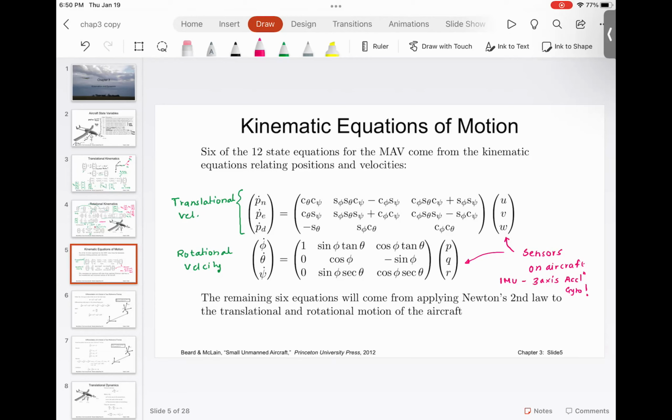All of a sudden, in a fraction of a second, if the aircraft performs say a 180 degrees roll, pitch, yaw type of maneuver, the Euler integration that you are performing will go out of bounds. So you use some type of Runge-Kutta or some technique.